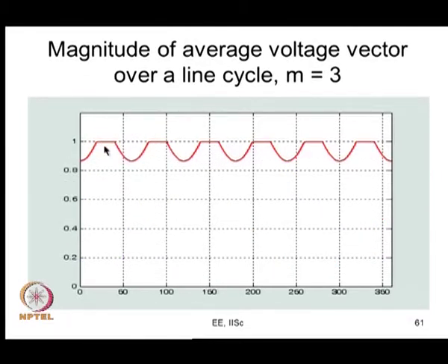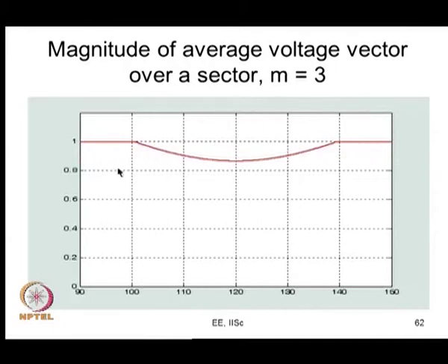What do you mean by magnitude being 1? An active vector is actually being applied. Here it is another active vector is being applied. So if you look at just one sector, up to this its active vector 1 is being applied, and then here active vector 2 is applied, and what is happening in between? There is switching between active vector 1 and active vector 2. So in all these subcycles you switch for active vector 1 and 2 only, null vector is never applied.